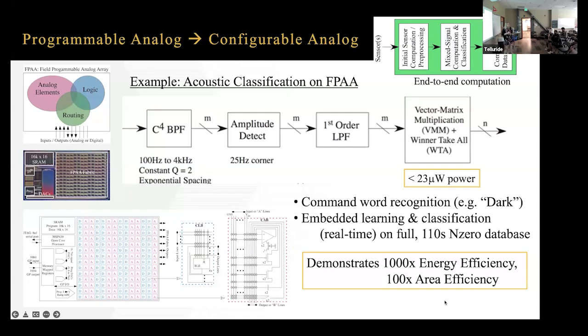Yeah, good question. So the MSP core is in sleep mode and you're running the classifier. When we're just looking at the power part of it, that was just getting that off, because the MSP itself is 500 microwatts. It's a pretty efficient one for this process, but everything in this process will take some energy. And we can go through exactly what the numbers are.